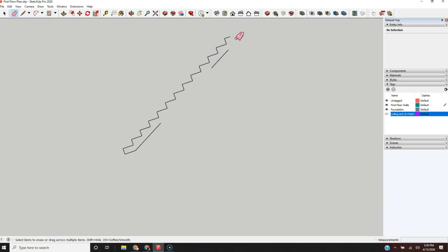And this is what's called a stringer. And this landing is 11 inches, and I want to have a landing that is 3 feet. So I need 2 feet more, 2 feet and 1 inch. So there we go. And this will be my landing.